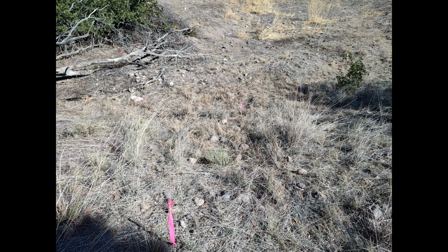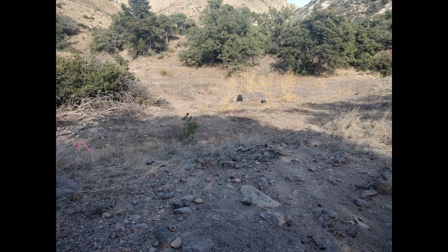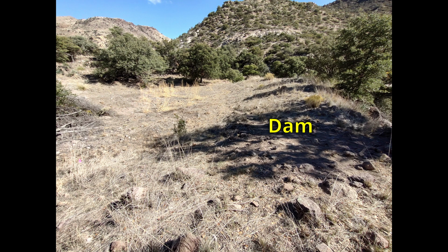Another source of soil that will be used to repair the dam will be the soil and rock removed from building the new spillway. We can obtain even more soil to repair the dam by removing soil from within the dry pond to form a deep basin where an aquatic safe liner can be installed. The rebuilt dam will be made level with a top at least 12 feet wide. The slopes on the inside and the backside of the dam will be gradual, averaging 10%.